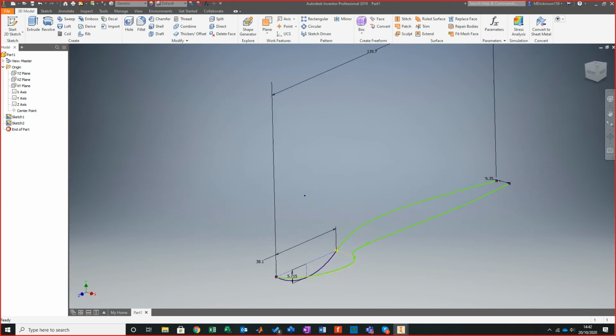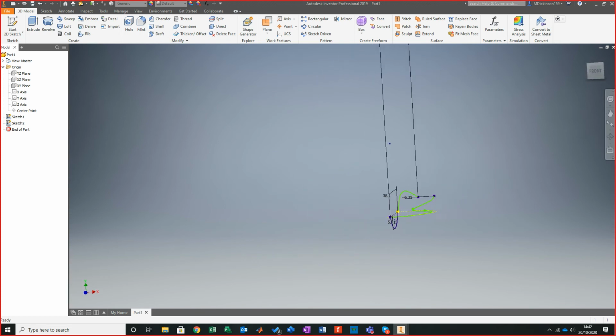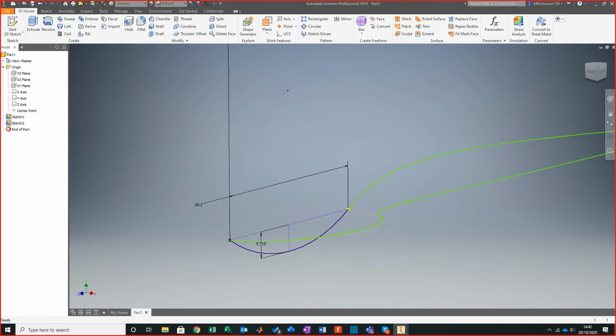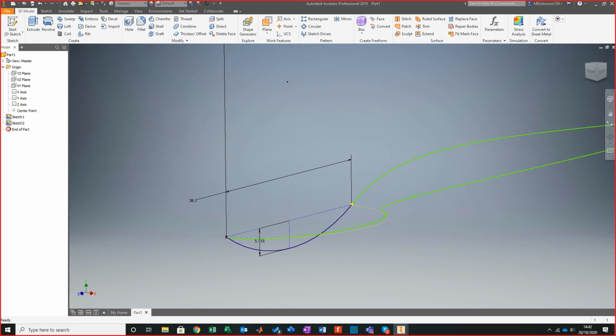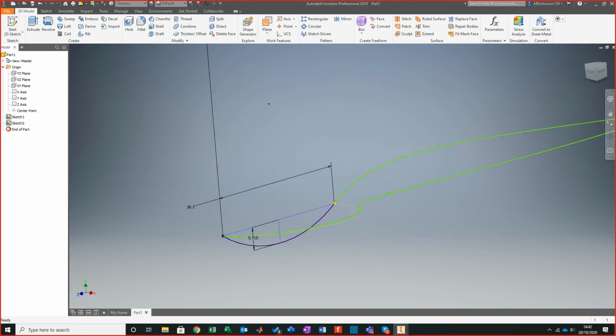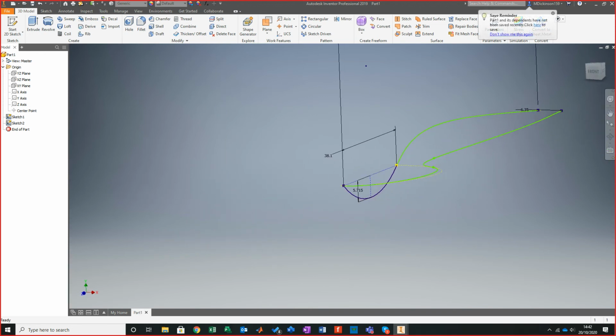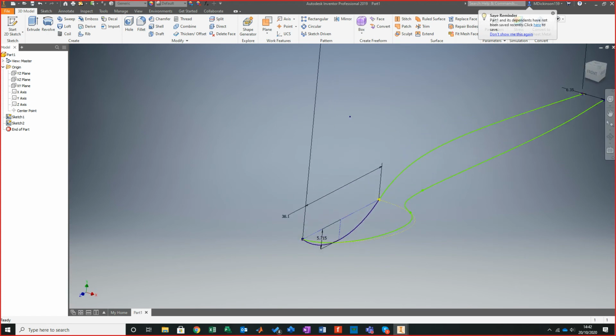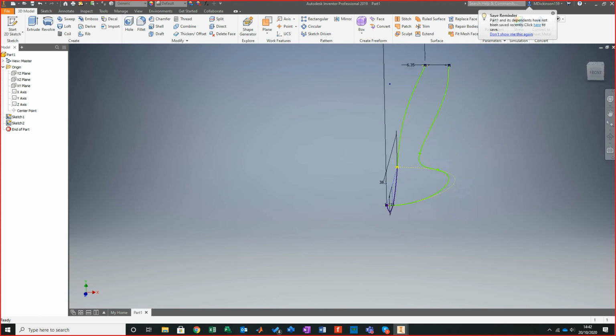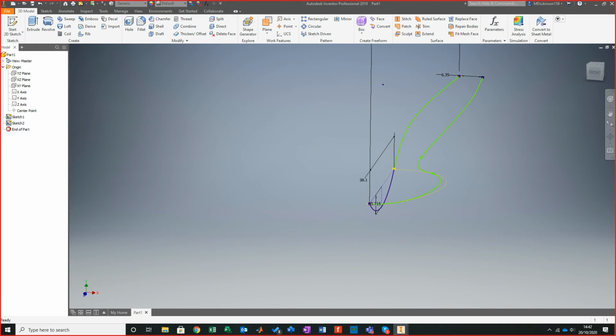We've now got 2 particular drawings, and last thing that we want to do is put on a plane on here, because what we're going to do is now create the profile of the spoon all the way up. Now the beauty with this is we can create an entire flow from tip of the spoon right to the top, and then look to start trimming things out.